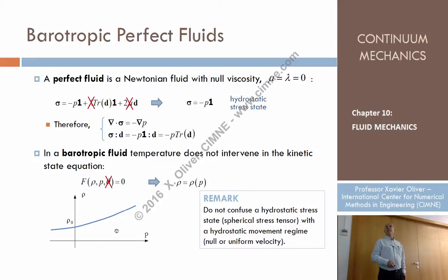It's incompressible, because then the density is always approximately the same. So incompressibility is a specific case of barotropic fluid. By the way, water, again, is not perfect either. It is also approximately, in our engineering cases, incompressible.